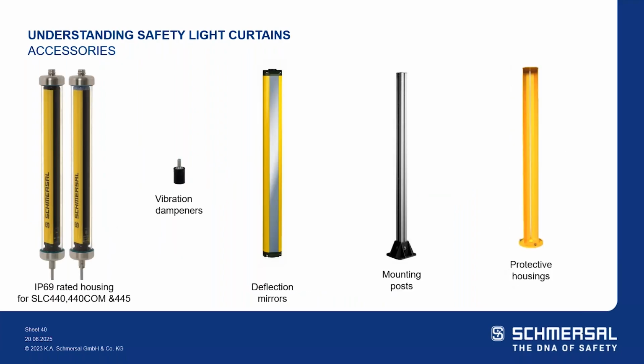Some additional accessories that are out there are deflection mirrors and mounting posts or stands, protective housings for both the light curtains as well as for the mirrors themselves. Vibration dampeners are included once you reach, oh, I've forgotten, I think it's 1,370 protected height, that are included in the packaging. Anything shorter than that, you can order them as separate accessories. And then the IP69 rated housings are available for your SLC 440, the SLC 440 COM, as well as the 445 series. And let's talk about that now.